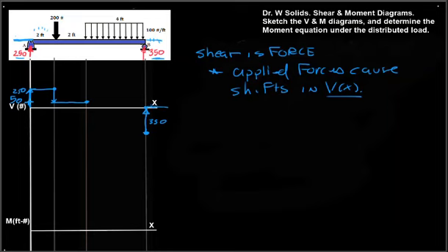So if X continued off the beam, we're back to no load. So these are called end conditions. And they're very useful when you're doing a quick sketch, because by knowing this end condition, I now know this function has to somehow connect itself between those two dots.